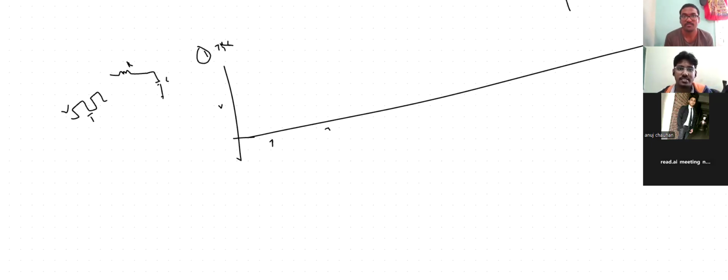That depends on the RC values, I guess. Charging will be fine. Because anyhow, I am taking T much greater than the time constant, we will consider that case. That is fine. But one more key point is if we change the duty also, it will remain the same. That is an important condition. Why? Because I will consider T much greater than, then if I change duty also, that will compensate that part. There is no issue. Then go to the second case.